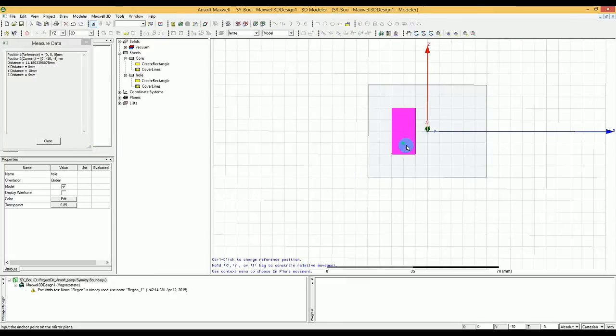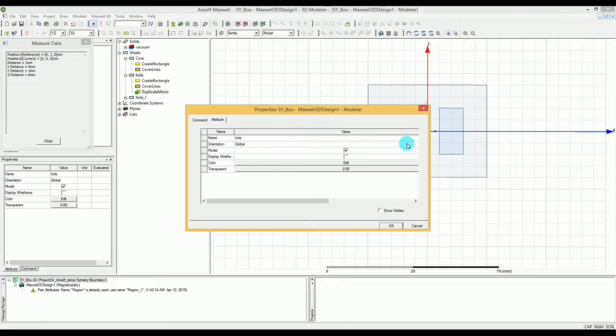So for the point, the mirror is going to be on 0, 0, 0, so that's the reference point for the mirror, and the amount is going to be 0, but in dy we want to have 1, and dz is going to be 0, so that's how it's going to get mirrored.